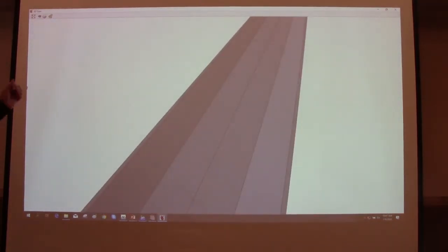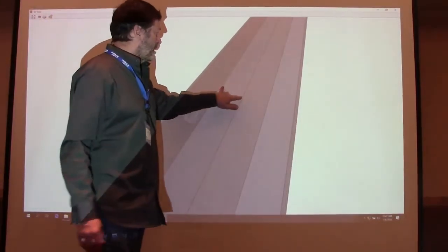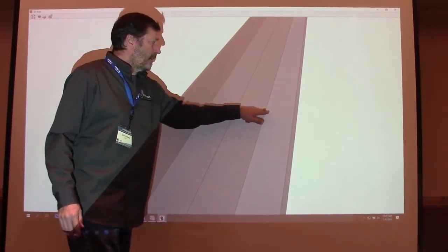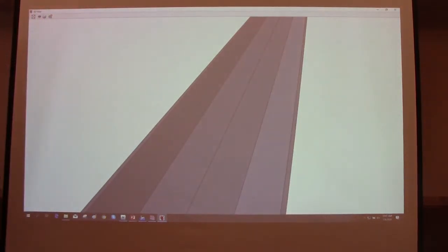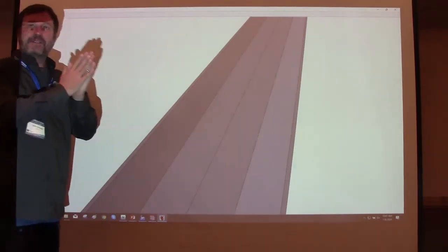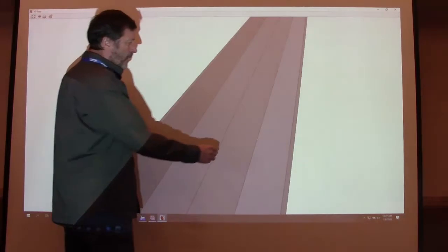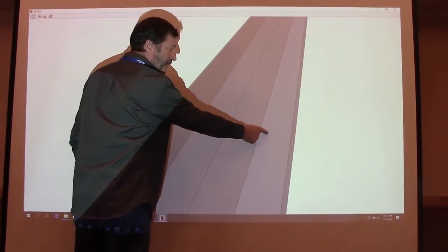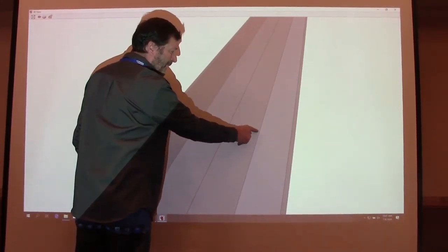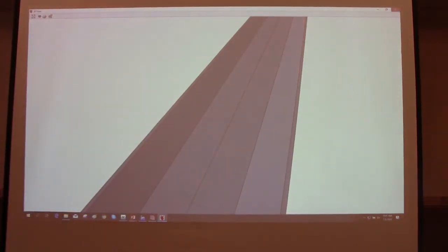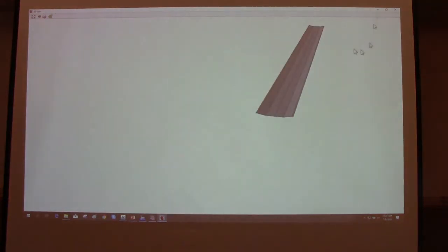The program is looking for the soundings within the center of the channel, and it's going to prioritize those versus the ones along the slope. So normally, like I said, sort works based on a 2D surface. So you most likely would have a shoulder sounding somewhere over here when you actually want to save the one that's within the channel. So it's just another way of thinning out your data, giving you another option.